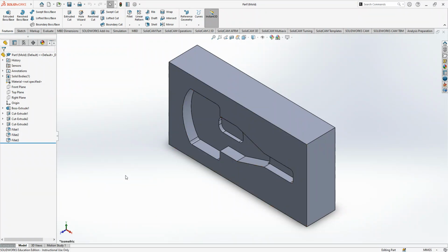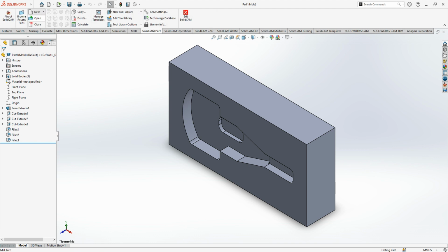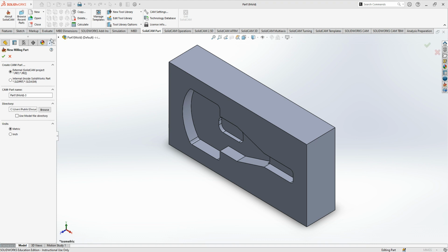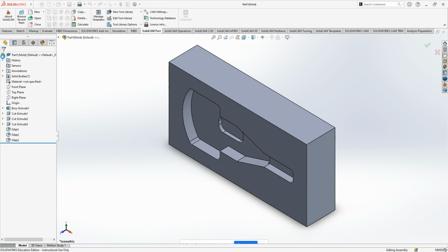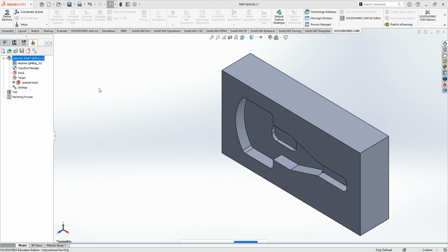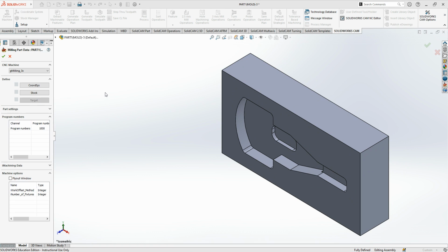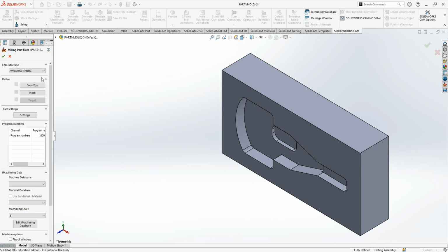Okay, so my name is Luke Perling, and I am about to demonstrate the milling process for part 1 of assignment 2. So to begin, we select SolidCAM part, go over to new, select milling, and here in this menu we want to make sure that external and metric have been selected. Close the window with OK. SolidWorks will now give us some options here, so we want to select our milling machine, the Fanuc model.